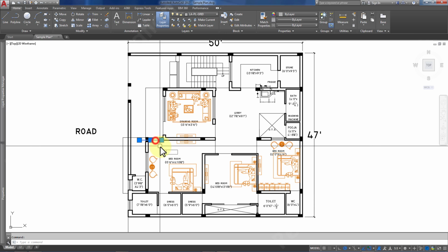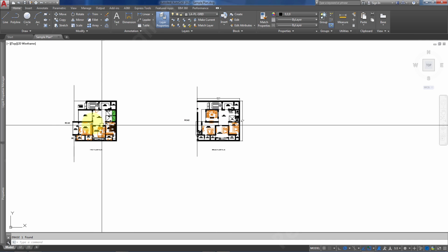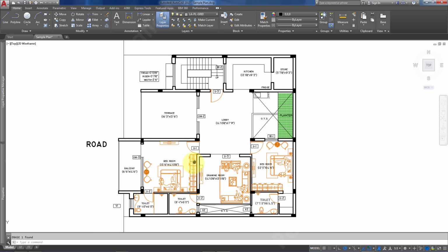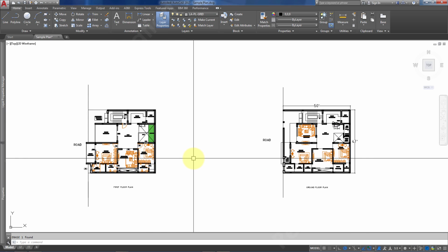As we all know, we create drawings in 1:1 scale in AutoCAD, but when we need that drawing to be printed on paper, we can't do that in 1:1 scale. We need to change it to a suitable scale depending on the paper size like A4, A3, A1 and others on which we want our drawing to be, and it also depends on what drawing units we are using in AutoCAD while drafting. So I will explain from scratch how we can scale the drawing while printing or plotting once your drawing is ready and fully drafted.